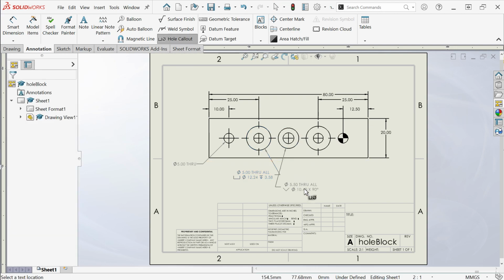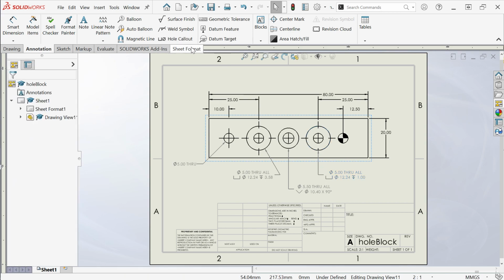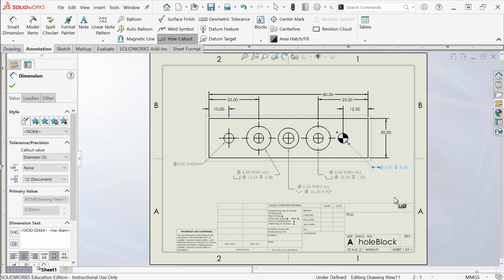As we go through, so you can see how to label all these holes correctly. Okay, that's the last one. So we just want them spaced out. And so you'll notice how it is standard to dimension all these holes. We start out with the overall diameter of the hole, and then note the diameter, say the counterbore or the angle of the countersink to be able to manufacture all these holes correctly.